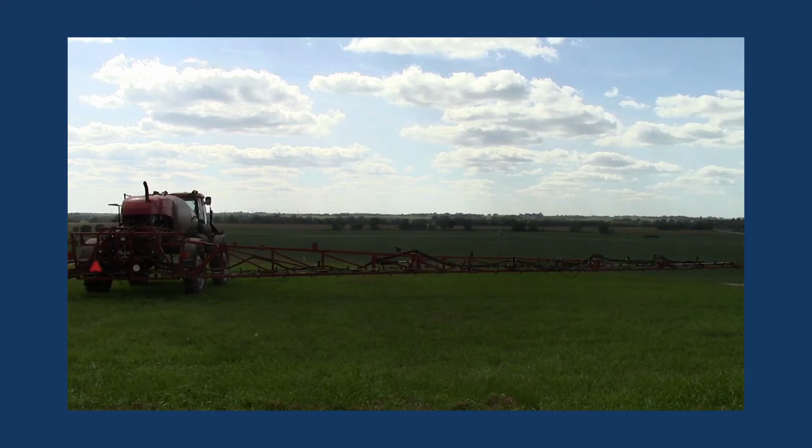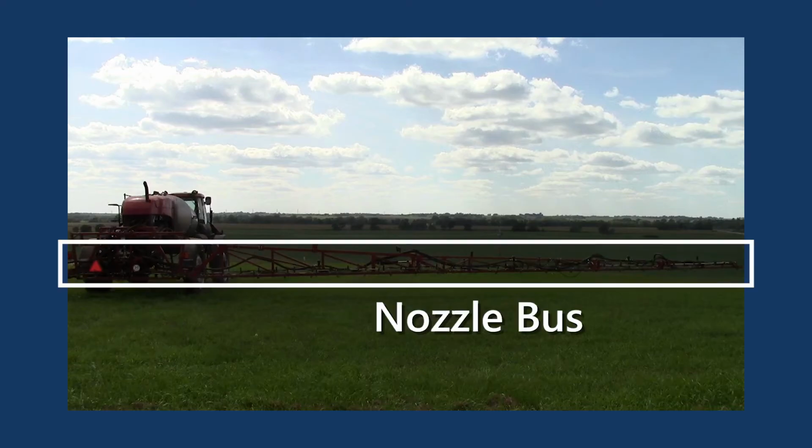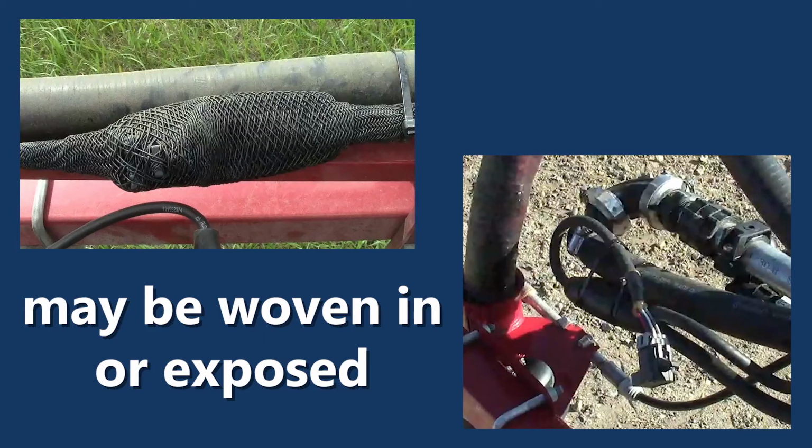Another issue may be because of a terminator. The terminator may have failed on you. Keep in mind there are two different CAN bus lines, and the CAN bus that you want to focus on would be the nozzle bus. It is the terminators that would be on each of the boom tips. There could be physical damage to the terminator, or it just could have failed.